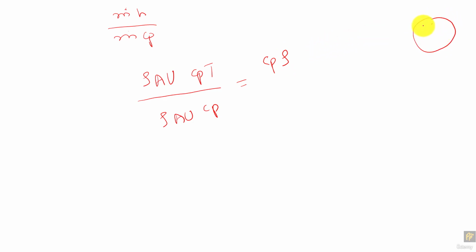Okay, so I can write down this equation as, for example, Cp rho, and because the velocity on any cross section would be varying in the fluid, this is going to be a variable, and so is the temperature; both are variable at different points. So u and T are functions of the position x and y, so they are variables. That's why I am putting them inside. So they are the small u and the T, and this area, because this is for a cross section, is going to be the dA.